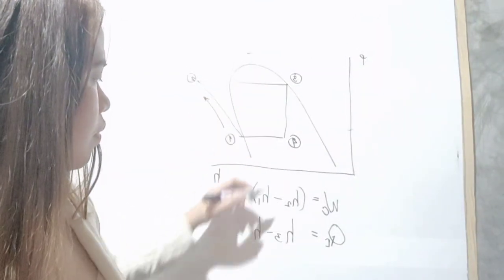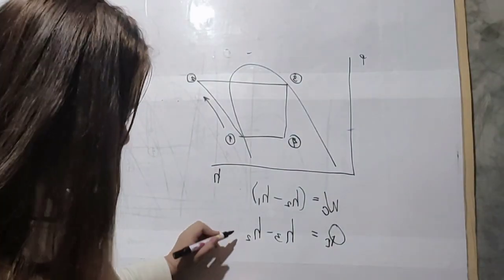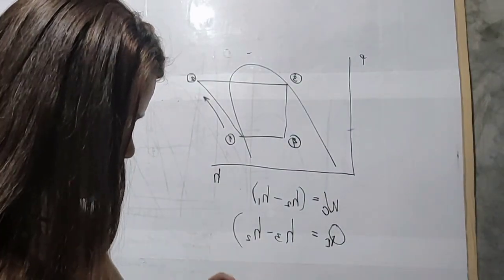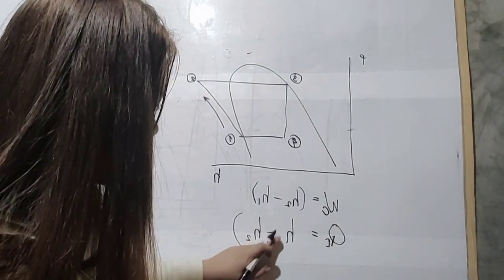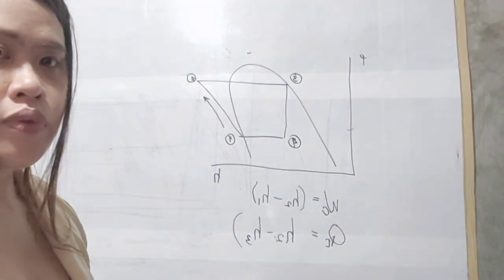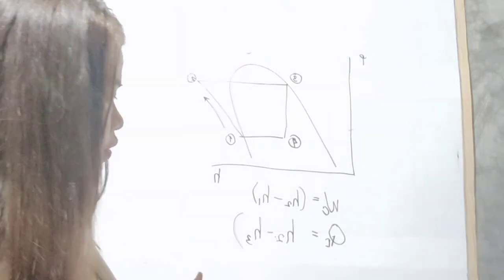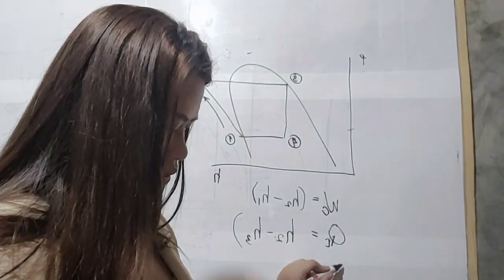Next is the expansion valve, which is considered a throttling process. Basically, we can get the value by getting into the steam table and doing interpolation if it is not available, where X is the quality or weight of flash gas per unit weight of refrigerant.